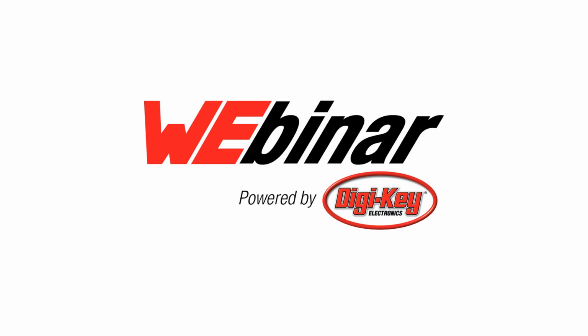Okay, most of the information was concerned with high frequencies. What if noise is at lower frequencies? Are ferrites not appropriate for noise under 100 kilohertz? Definitely. In this presentation we have focused on high frequency, but of course we also have chip bead ferrites designed for low frequencies. It will be a matter of taking a look at exactly what chip bead ferrite may be good for your application.